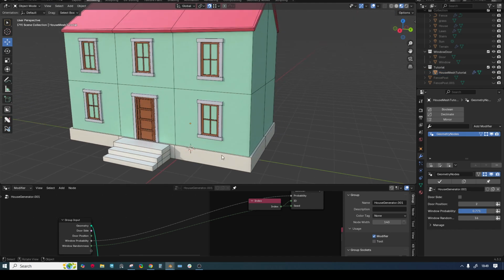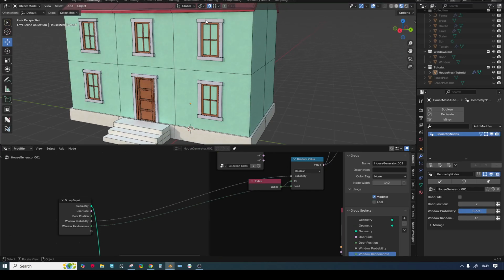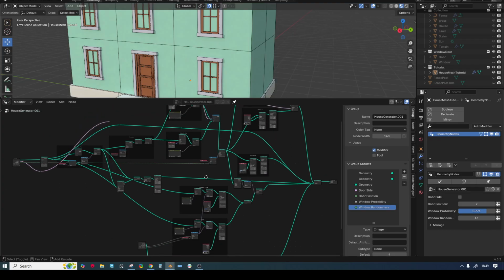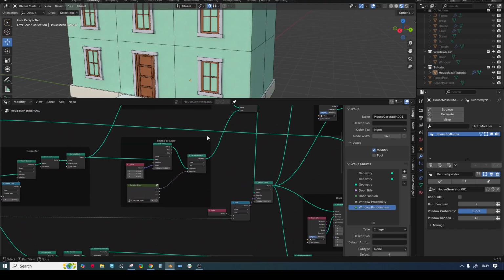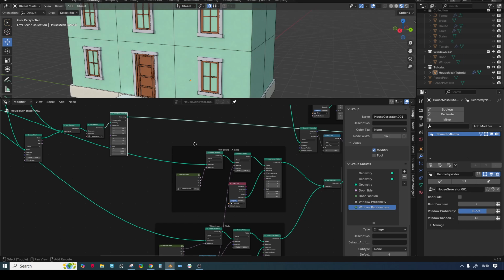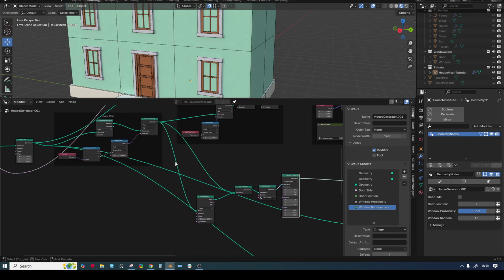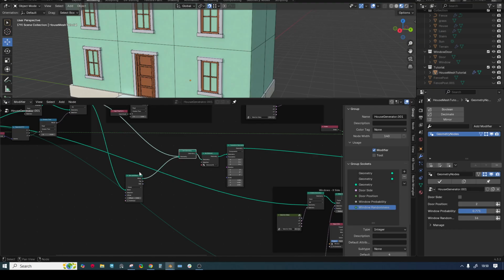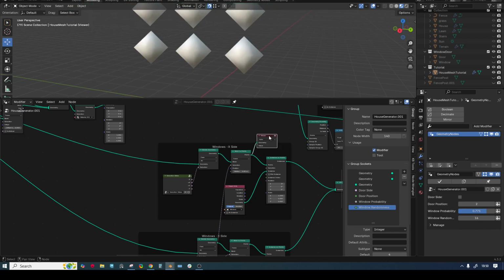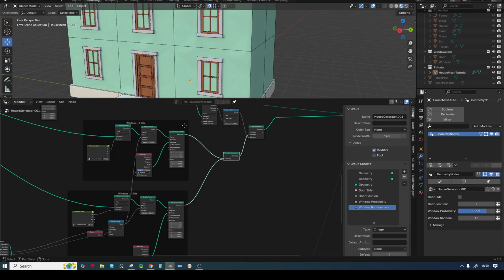and you can go a bit further. In my showcase model, I also had a Boolean cut out of the window, cutting from the base mesh of the house. So you can go back here, identify the window points, instance a cube and also use a Boolean mesh node to cut through the main mesh. So let's find the windows.